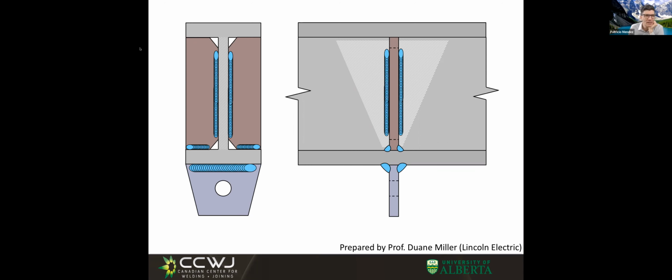Thank you, Wes, for answering. But the funny thing is, the answer is no. And you know why? Because whatever load we would be transferring to the flange would be on the compliant part. So this part would be bending without giving us much strength.